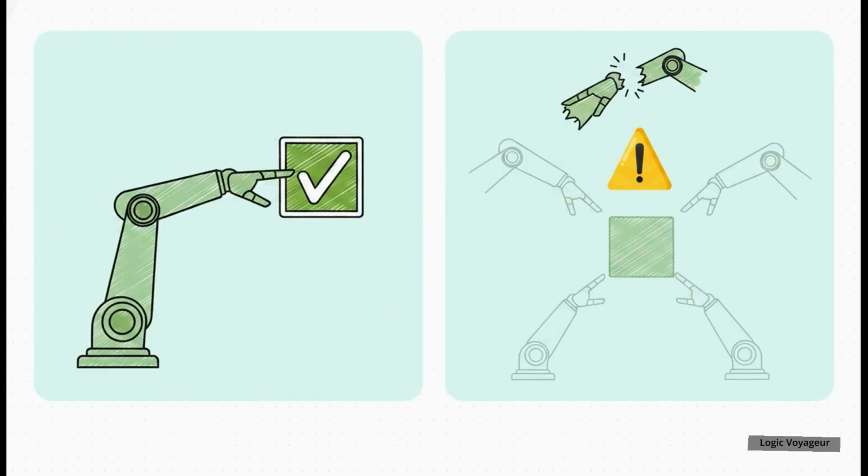But here's the catch. Inverse kinematics is a computational minefield. While forward kinematics gave us one clean, easy solution, a target position in inverse kinematics might have multiple postures to choose from. Think about it like reaching for a cup. You can grab it with your elbow pointing up in the air or resting down near your side. The robot has to make that same choice. And worse, the target might yield no solution at all, simply because it's physically out of reach.